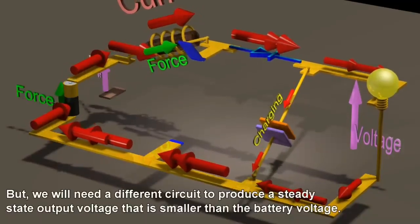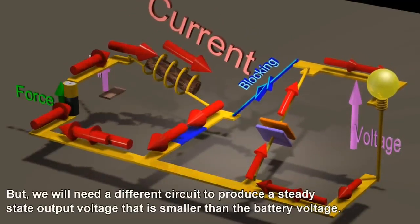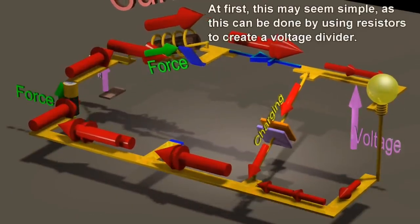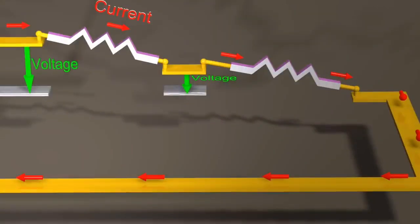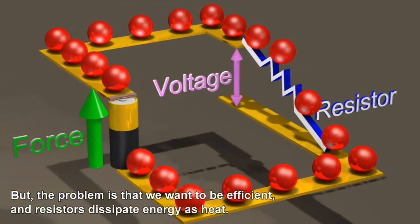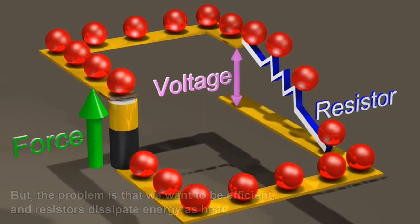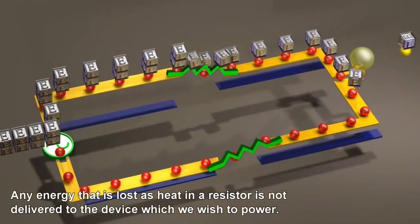But we will need a different circuit to produce a steady-state output voltage that is smaller than the battery voltage. At first, this may seem simple, as this can be done by using resistors to create a voltage divider. But the problem is that we want to be efficient, and resistors dissipate energy as heat. Any energy that is lost as heat in a resistor is not delivered to the device which we wish to power.